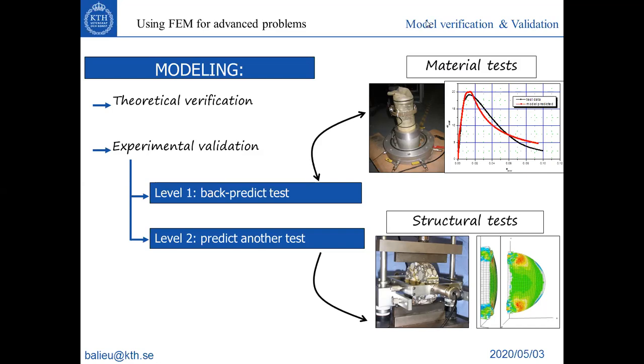So here there is a certain geometry of the specimen. It's like a cylinder with a certain diameter. If you change the geometry, if you take a wider cylinder, you will get the same material parameter, same peak stress and same damage evolution. Of course, if we discuss stress strain, that's why it's a material test. It's a test able to identify intrinsic material parameters.